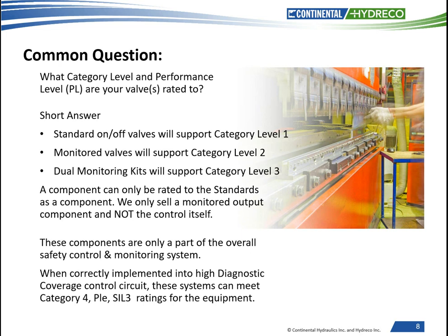Monitored valves will meet and support Category 2, validation signals. Dual monitoring kits will meet and support up to a Category 3. Category 3 was redundancy. Remember, we only sell components that are part of the safety circuit and not the safety controller or control architecture circuit being used.